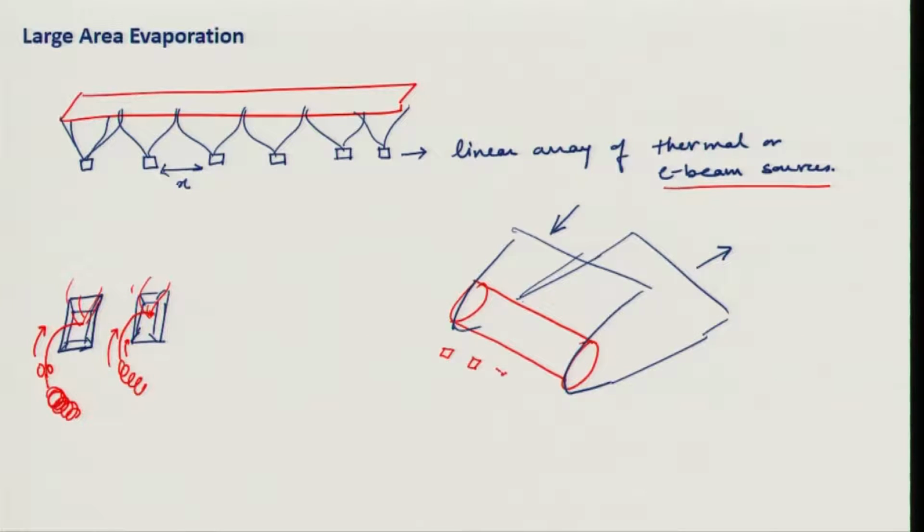as before in a linear array at one point, such that when you evaporate it forms a uniform coating, right, and you can adjust the thickness of the film by adjusting the rate of pull of this flexible substrate, which is usually called a web.